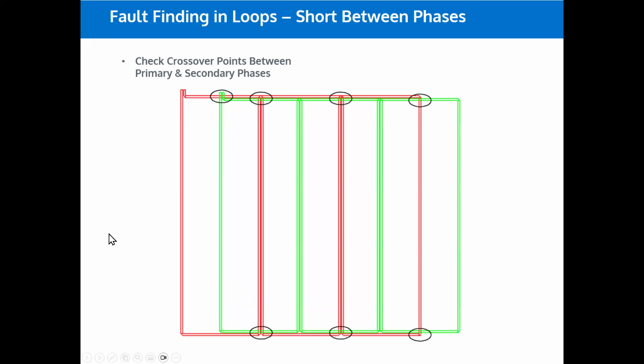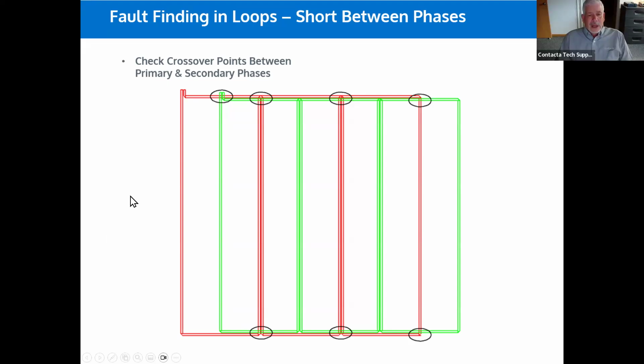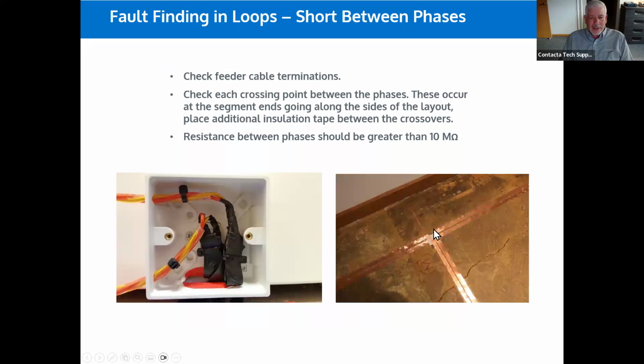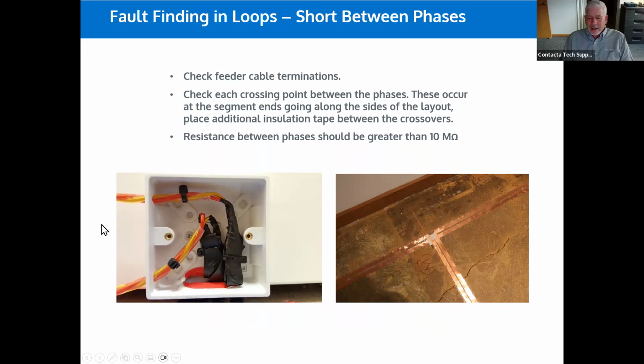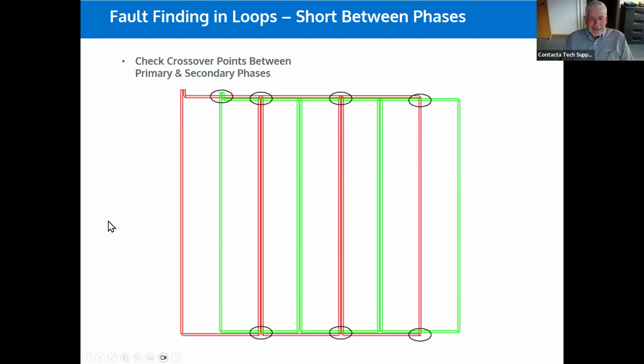Dave, is there anything you want to add to that? Are you quite happy with that? Well, a good product to use when you're installing the flat wire to keep a barrier between the two phases, or when one wire crosses over another, is called 3M 3903 vinyl duct tape. It tears very nice and straight and easy, and it puts a piece of thin vinyl between the two wires that you're overlapping or crossing. That's effectively what that is. Yeah. It comes in all different colors, and one roll will last you a lifetime.